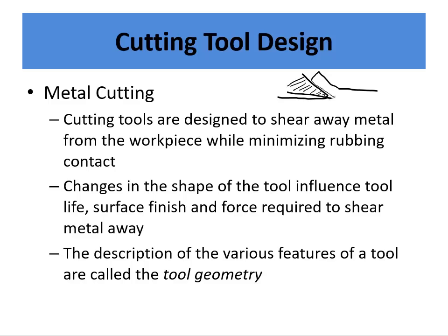The area underneath of here, and let me just add some color to it so we can see, this area right under here is actually clearance. You don't want it to rub there, because if it's rubbing and not cutting, it's just generating friction, which generates heat. So you don't want that.